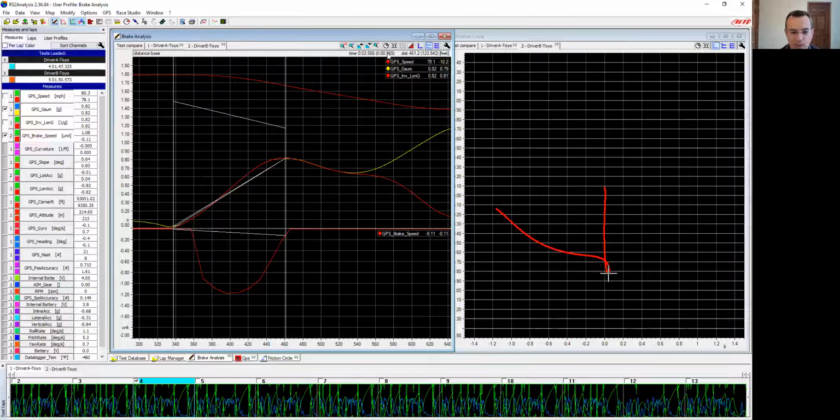And I want to make sure that you guys understand that just because 0.5 is a target doesn't mean that's possible for everybody, right? In this particular case, we're talking about Spec E30 cars. They're on the more softly sprung side of things. If you just jam that brake pedal as hard as you can, as fast as you can, you will shock the chassis and it may go instantly into ABS, right? That's not the type of mode that you want. You have to have enough of a progression in applying that brake pedal that you don't shock the chassis.